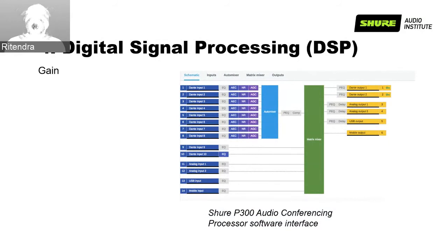As we discussed DSP processor blocks, in this slide we are going to demonstrate the audio quality you can have after applying audio processing in the DSP blocks, right? So the first thing is gain and gain structure. Gain is basically the adjustable level at the input stage of a device. Maintaining appropriate gain structure is essential to create a good sounding audio system. Poor gain structure can lead to problems and noise issues, including artifacts and distortion in the audio signal.